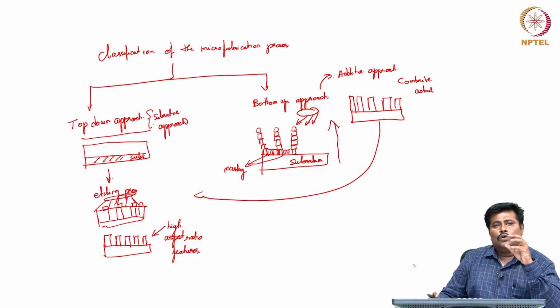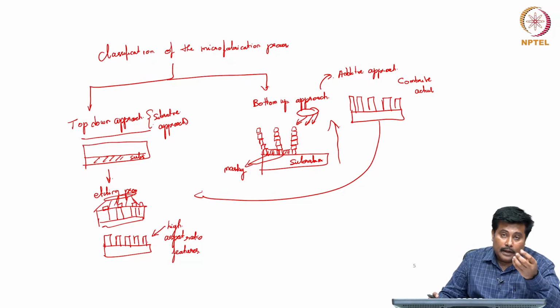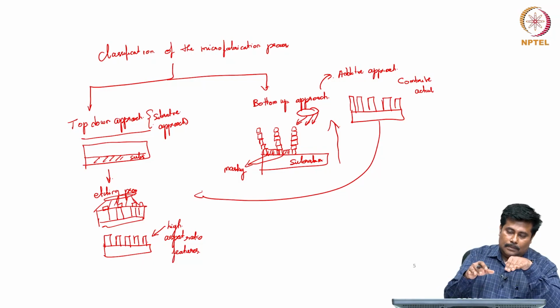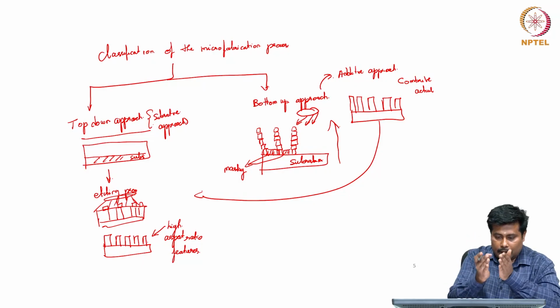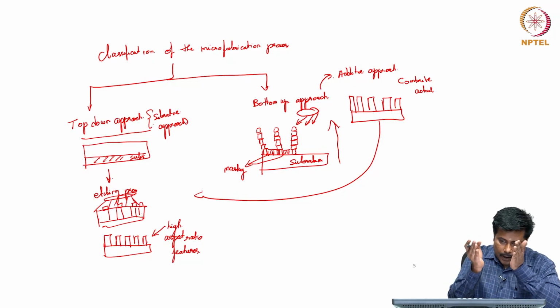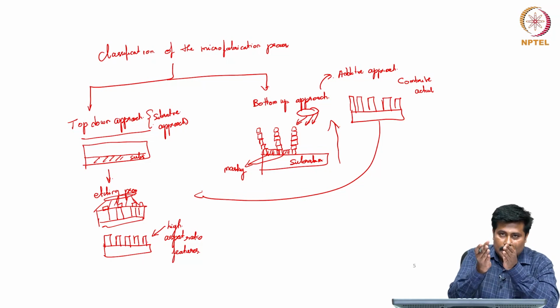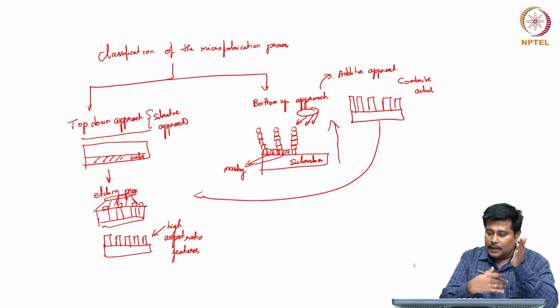We can also consider electron beam lithography or electron beam based etching, which can be used for efficient etching applications. We can also go for certain chemical treatments which are being effectively used for etching such kind of features. So, in all these cases, either we use a mask, or in certain cases we try to focus the energy which we are using, so that these energies can be efficiently used for etching related